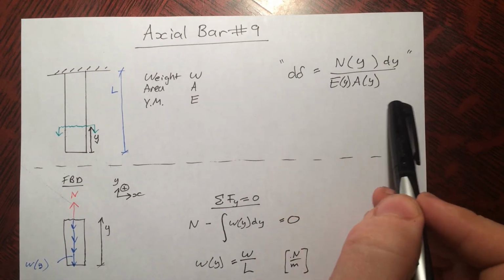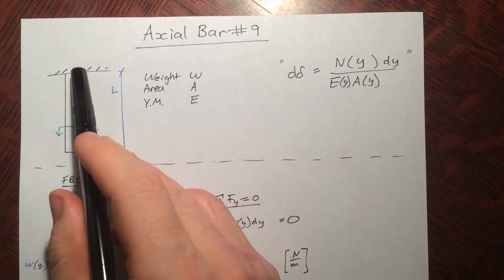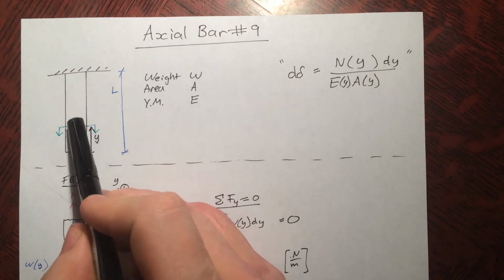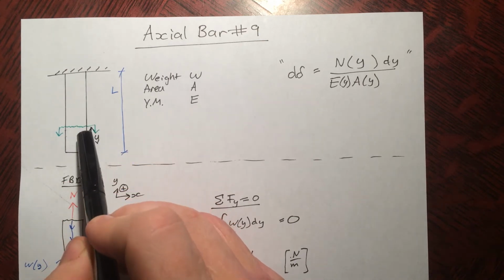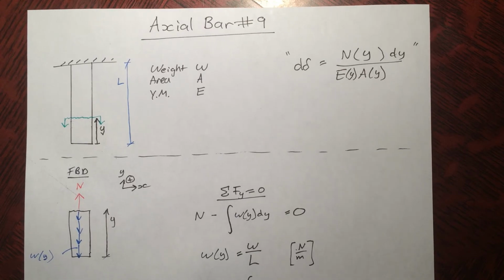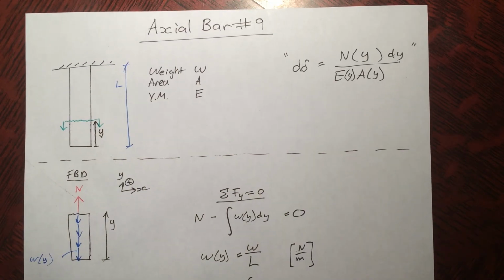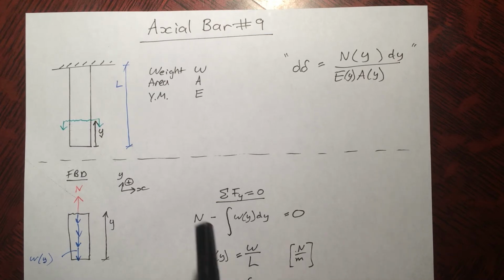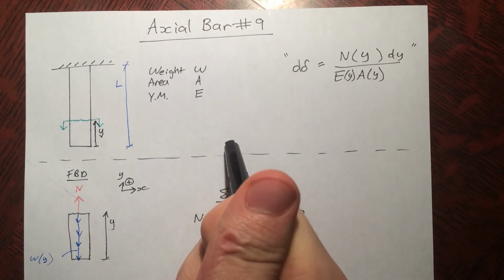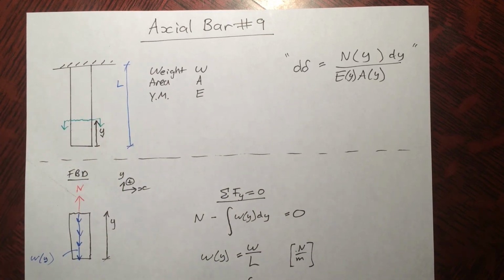We realize it's a differential equation because our weight is not applied at one point, it's distributed. And I also want to note, if you have some sort of force per length, it's not a good idea to evaluate the force as a number and just plunk it in the middle, because more often than not that will get you to the wrong answer.